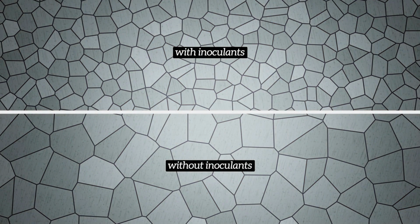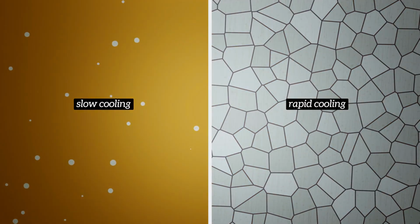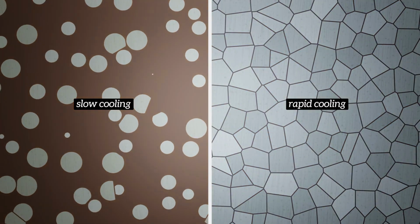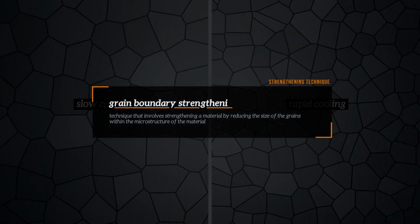Another way we can do this is by controlling how fast the metal is cooled. If a metal is cooled very rapidly, nucleation occurs at more locations and the crystals don't have much time to grow, so the metal will end up with a finer grain structure and will be stronger as a result. Controlling grain size to strengthen a metal is called grain boundary strengthening.